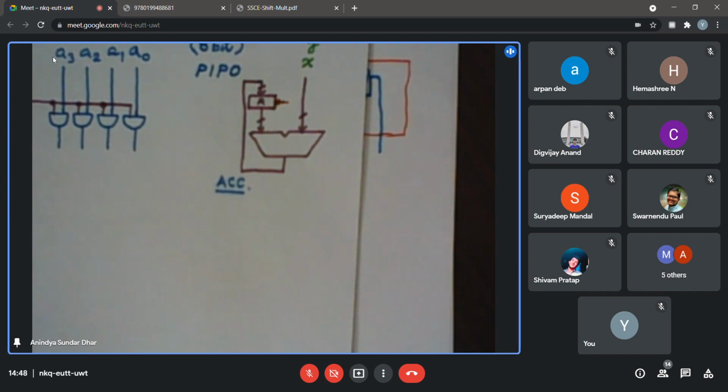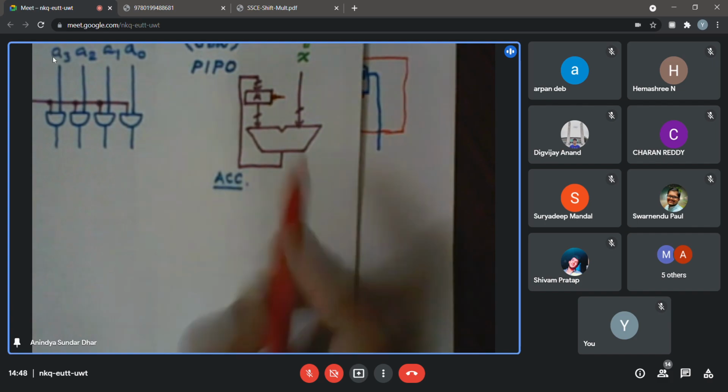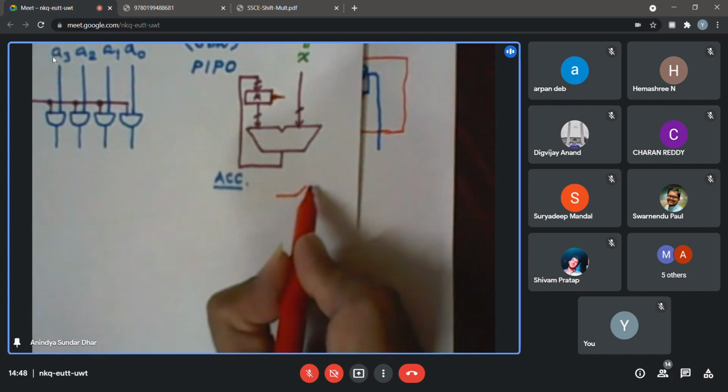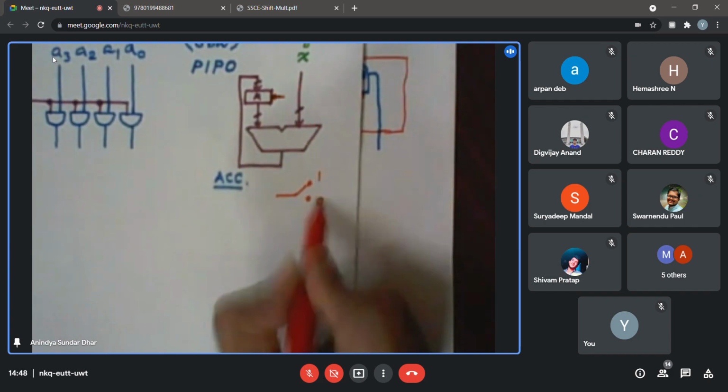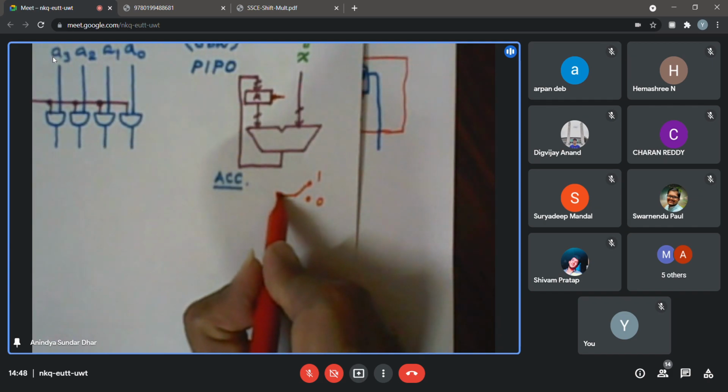Particularly if you have used the ASCII keypad, then on the same submenu you will find three things. One is the ASCII keypad, one is the hex keypad, and there are similar switches. There is something called a logic switch, which looks like this, basically just a three-terminal switch. One side is showing as 1, this side as 0. But you need to connect only this common point.